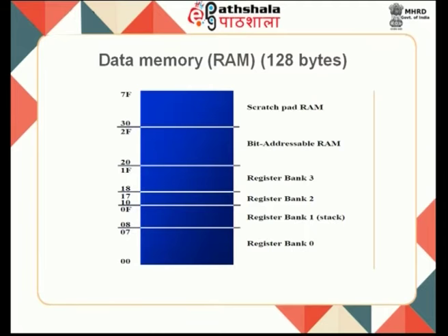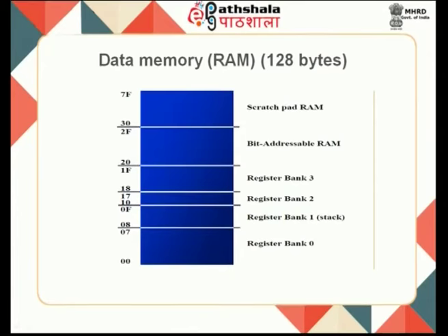So, when I am looking at my memory, this memory is very important in the 8051. As I told you, this particular memory has only 128 bytes, that means only 128 words can be stored in the random access memory of your 8051, where as I told you from 00 to 7F I will be in a position to hold all the data. This is the address, and in that address only my data is stored, and each data is of 8-bit width.